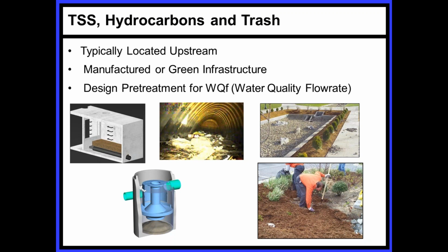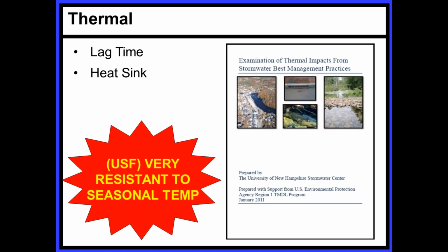The recommendation I have for treatment is that you size them only for that first flush, for that first part of the storm. If you size them for your major design event, you are making them very large, very expensive, and if the peak flow is exceeded, they'll wash out, and then any benefit they have has been negated.